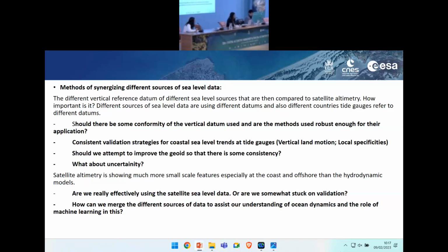I would like to add something about the current meters. That is something more like an oceanographic question, because with the current meters, or the ADCP, you are measuring the absolute velocity. For an oceanographer it's really interesting to understand the behavior of that current. For example, if you are measuring the velocity in the whole water column, with statistical methodology you can know which is the percentage due to barotropic component or baroclinic component.